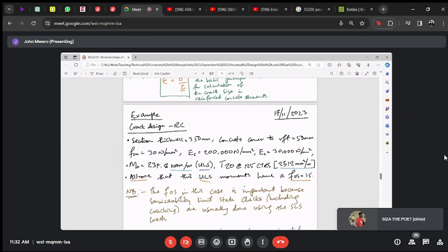And if for this ultimate limit state moment, we need T20s at 125 centers to be able to carry that moment for the ultimate limit state. So then we said, let's assume that the factor of safety is 1.5, the factor of safety that has transformed the ultimate moment from a serviceability limit state moment to an ultimate limit state moment.